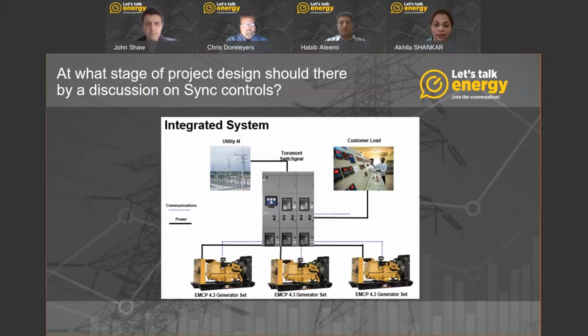This, our second solution, offers flexibility and customization in the design of controls. In addition to controlling generator sets, the PLC-based controls can also integrate automatic transfer switches, UPS, and other balance of plant devices like the fuel tanks, chillers, battery systems, etc., and also communicate with the building management systems.